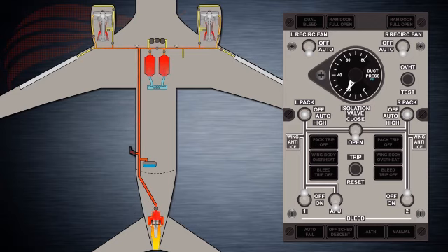There is no pressure indication for the APU duct. However, as we mentioned before, the APU bleed air flows into the left side of the aircraft pneumatic manifold, meaning its duct pressure can be obtained with the duct pressure indicators we also discussed previously.